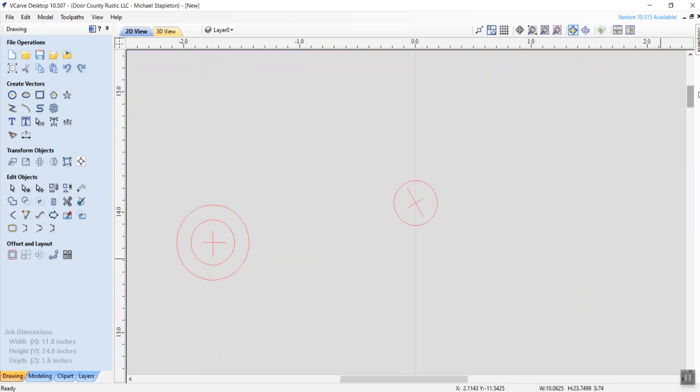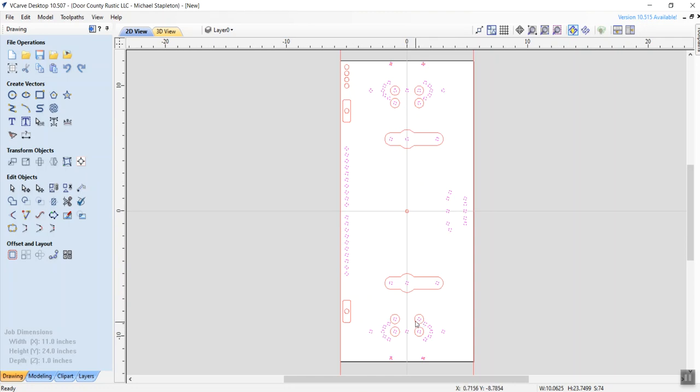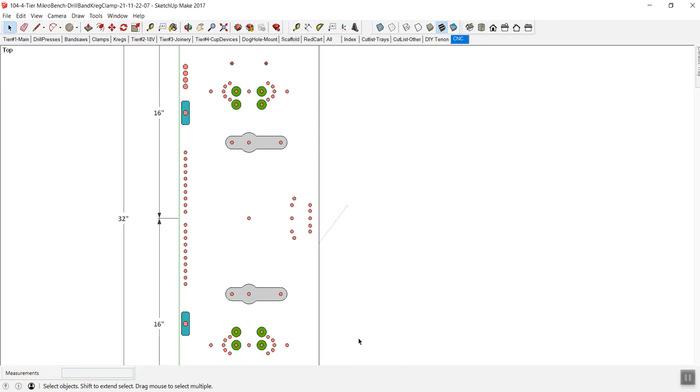And those are off the chart anyhow. So view, zoom to drawing. Now I'm going to zoom in just one more time just to double check. And then the only one I was a little bit nervous about is these holes here. Were they 1/4 inch? Because I don't want to do a single pass or 2 passes on something that's wider or larger diameter than 3/4.